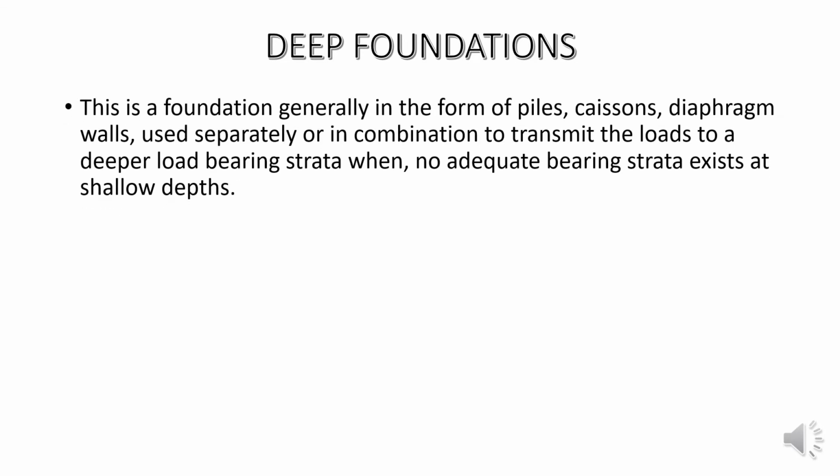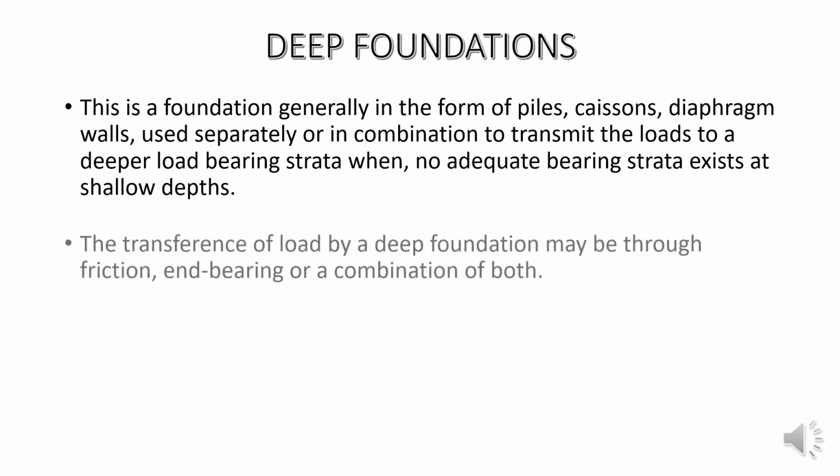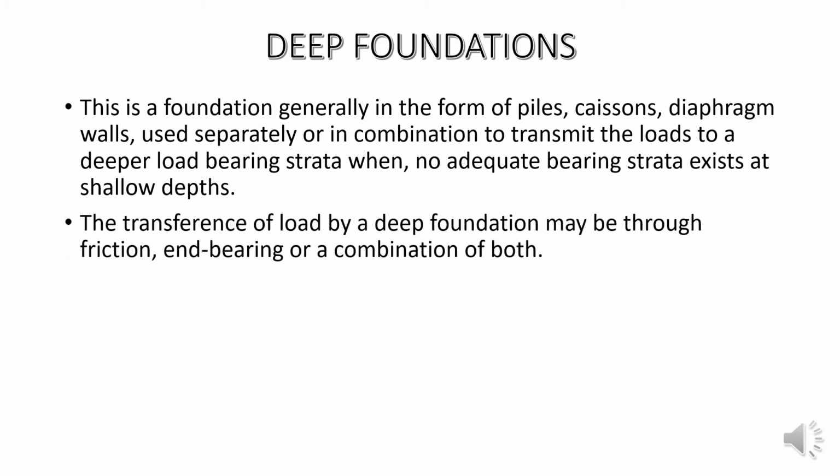This is a foundation generally in the form of piles, caissons, diaphragm walls, used separately or in combination to transmit the loads to a deeper load bearing strata when no adequate bearing strata exist at shallow depths. The transference of loads by a deep foundation may be through friction or end bearing or combination of both.